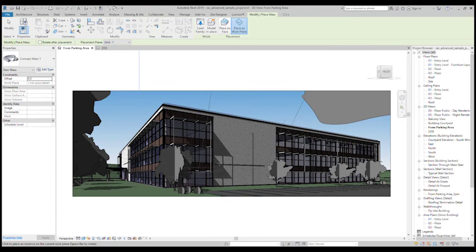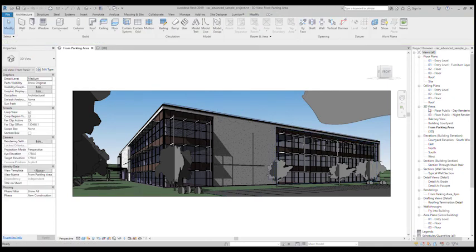Now, once you've opened this project, you will see that it's basically in 3D view, and we don't want to place this mass in 3D view. We want to place it in a plan view or something. And so here are all of our plans currently set up and our levels. And for the third years, I'll go through how to set that up easily.